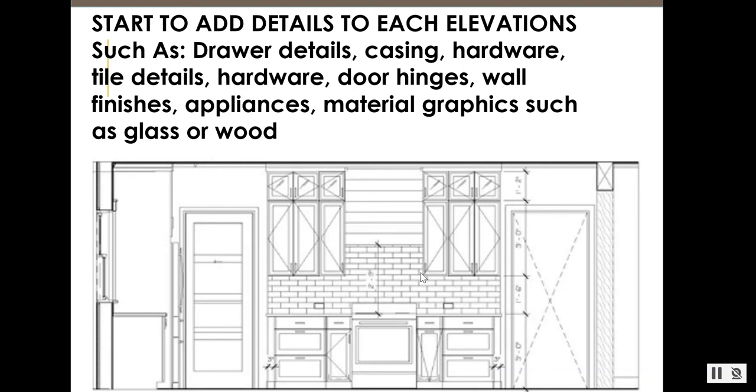Then once you've gotten those horizontal lines in, you start to carve out your space according to that floor plan. So when you know there's an opening perhaps in a space, you start to realize you have your 3 feet or 36 inches here, your 18 inches of backsplash, your 3-foot cabinets. These have uppers. You start to carve in your space according to your floor plan. You get in the cabinetry, you start adding in architectural features such as windows and doors. This is a profile of a cabinet right here. Add the toe kicks. So this is when we start to carve in the space.